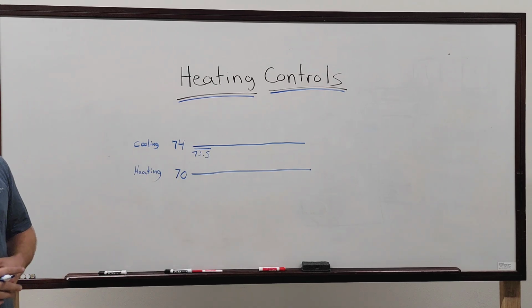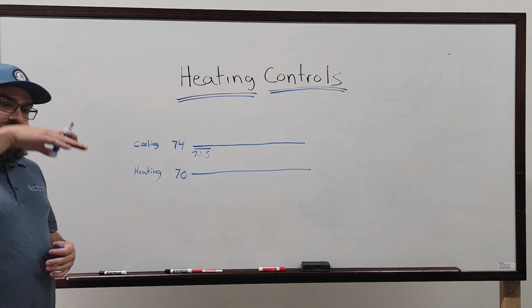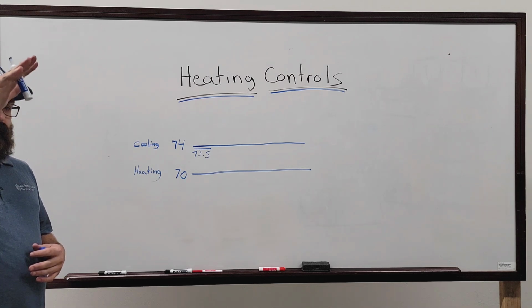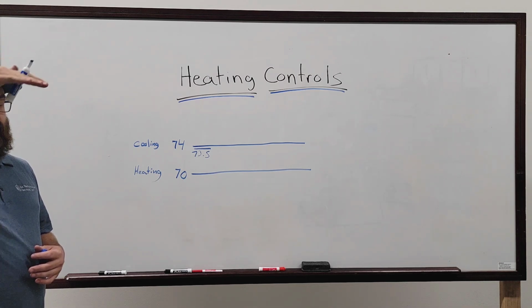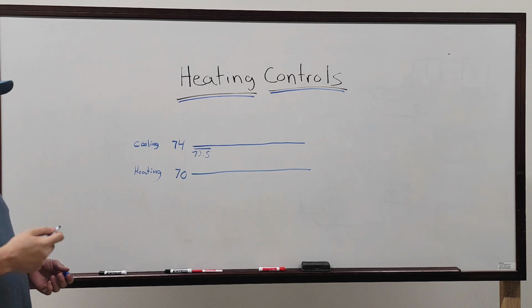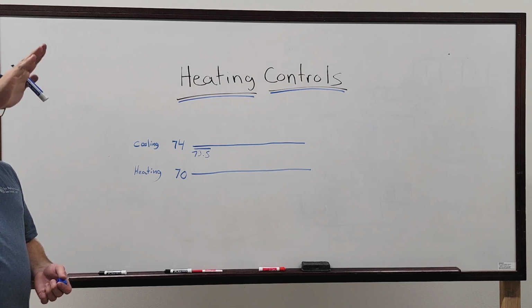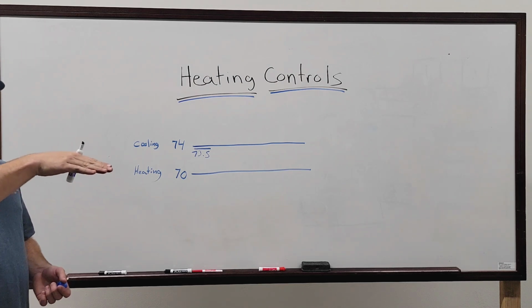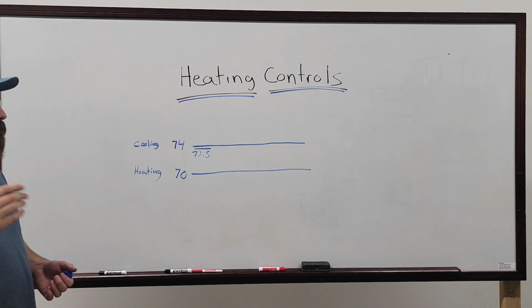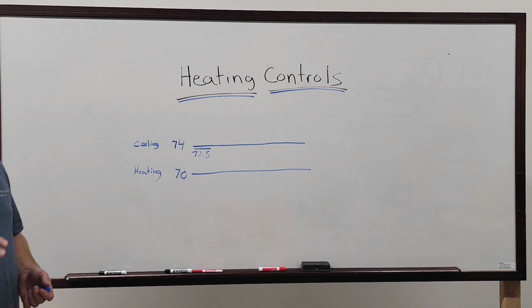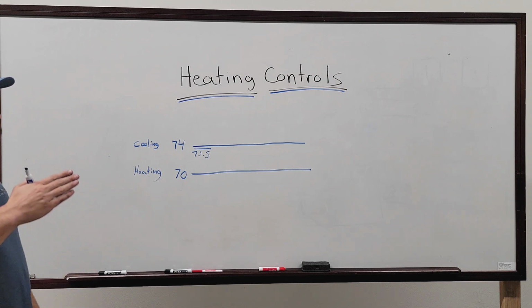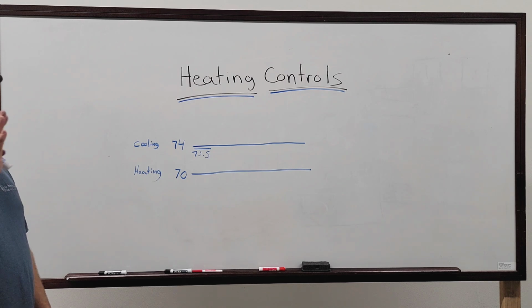It's pretty quick because they're proportional algorithms, right? Like I said, they're chasing that wave. The further you get away from a level line, the faster it reacts. It's proportional, okay? And it's proportional over time. The longer you sit closer to that peak, the faster it reacts. So it varies based on time and differential. So if you are staying hot over a long period of time, it will continue to increase your cooling command.